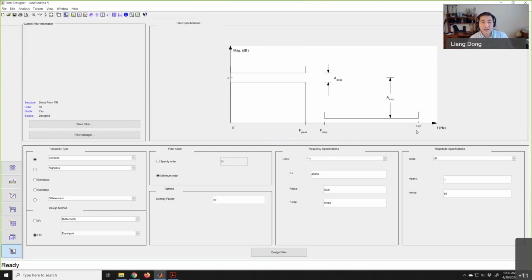Well, pi is the Nyquist rate, which is the sampling frequency divided by 2. And as we know, sampling frequency has to be twice as high as the highest frequency in the signal. So indeed, this stands for pi if you look into the radians. But if you give the unit in hertz, that is fs over 2. That's the sampling frequency over 2.